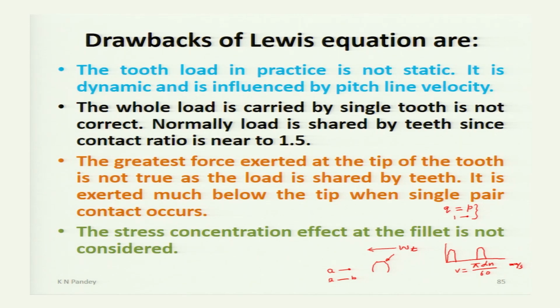So, at A, when a load Wt is acting, it is shared by another gear tooth near the point of disengagement B, because that pair of gear teeth has not yet disengaged. It is at the verge of disengagement, but it is not disengaged, and so it will share the load.